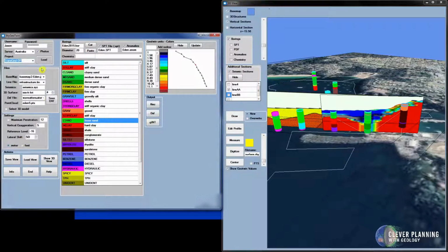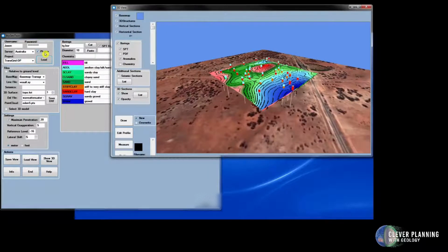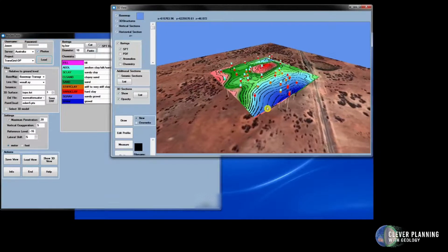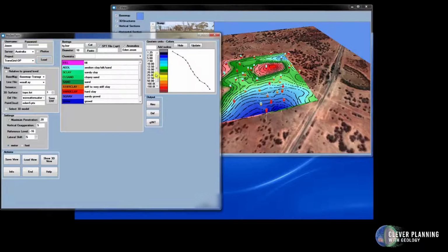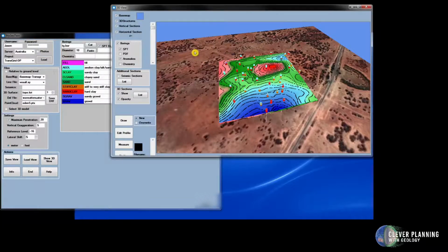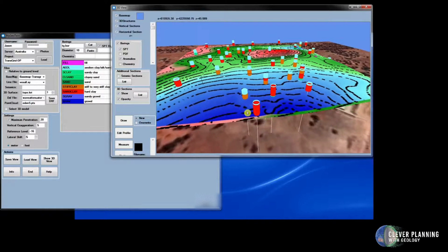Positioning errors are quite common and quite difficult to detect in PDF borehole reports. As such, an error can be queried quite late into the design and even construction phases. Here we examine a land site for a transmission tower. Data was collected over 2 days and processed on the fly. In this case, we have 2 borehole campaigns undertaken several years apart by 2 different contractors.